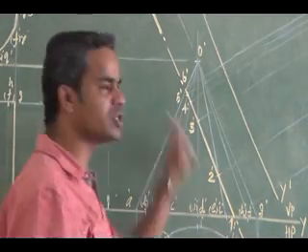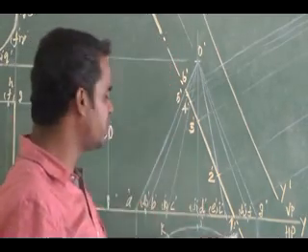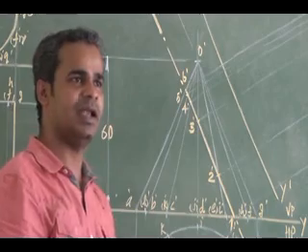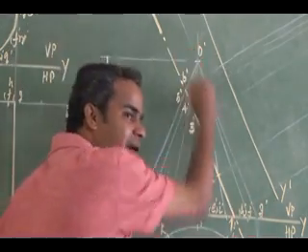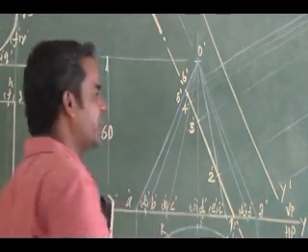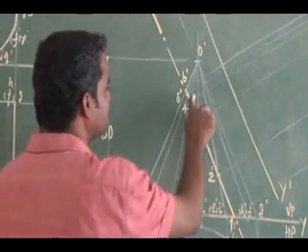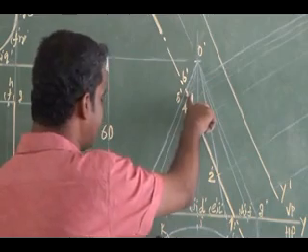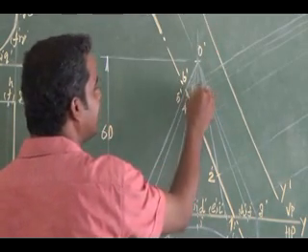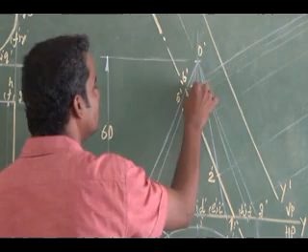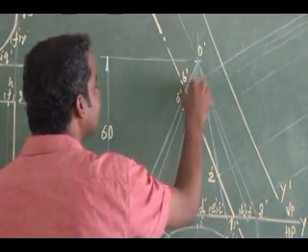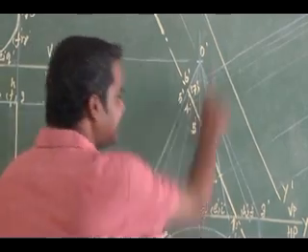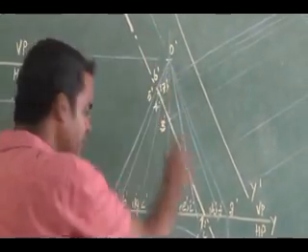So it cuts 5 visible generators and a base. Right. Then it cuts 4 hidden generators. So come back on the cutting plane, searching for hidden cutting points. Then it cuts the hidden generator LO, so that is my cutting point 7 dash. So that is my hidden cutting point. So you can mark it inside bracket. Then it cuts the hidden generator again along the cutting plane K.